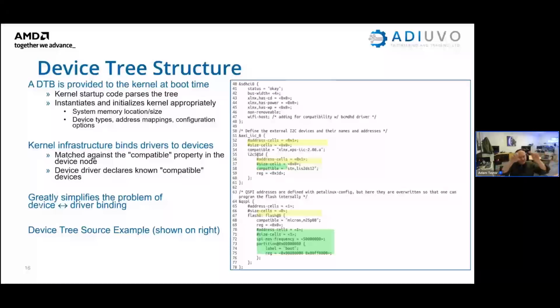If we have things on the board that are connected to the FPGA, be it on the MIO pins or the PL pins, it doesn't have any understanding of them. We understand it because we drew the schematics, so we know what's available, but PetaLinux and Vivado don't. So we have to add that little bit of information if we want to say that you've actually got a driver for this device that's connected to your I2C. Hopefully that makes sense to everybody.